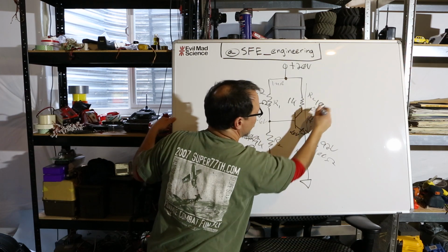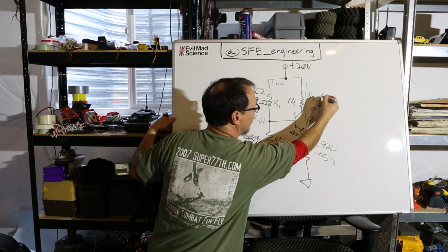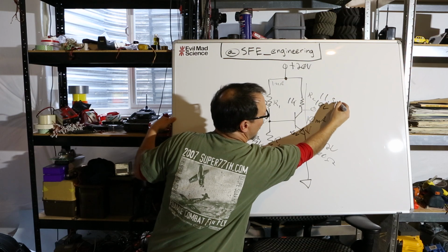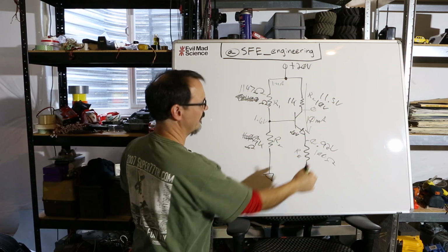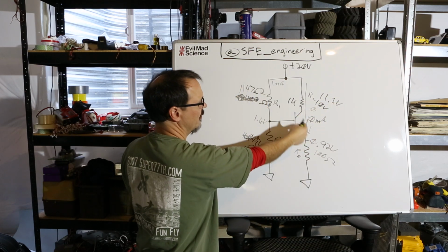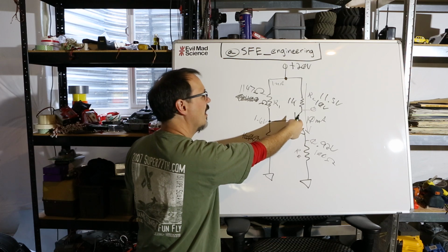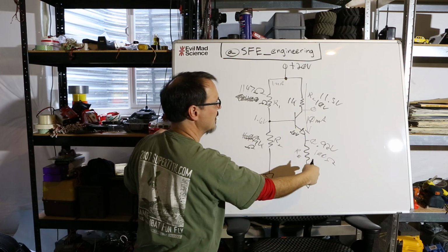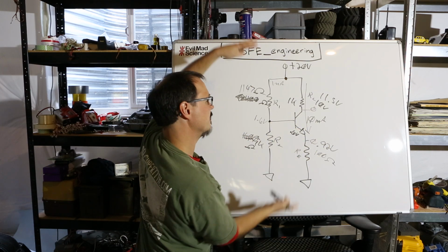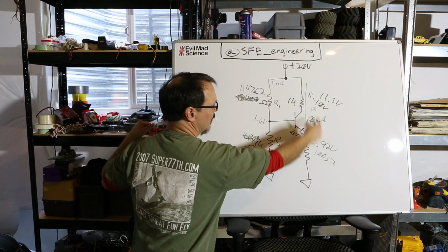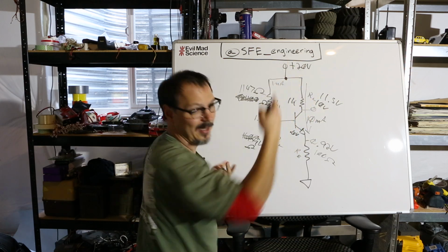My bias voltage was sitting at about 11.5 volts, right? So I've got smaller current here, which means this thing is turned off a little more, and so greater resistance, and so the voltage divider acts, greater voltage across this than that. That's why I got 11.5.